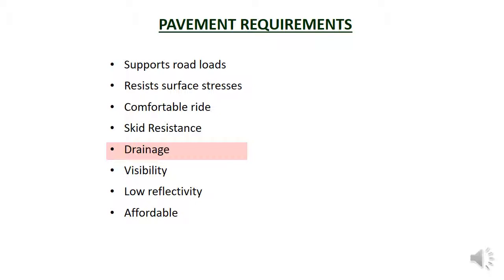Water soaking into the pavement structure can result in the structure not being as strong as it needs to be and failing. Therefore, the surface of the road needs to be watertight to prevent the intrusion of water into the road surface.